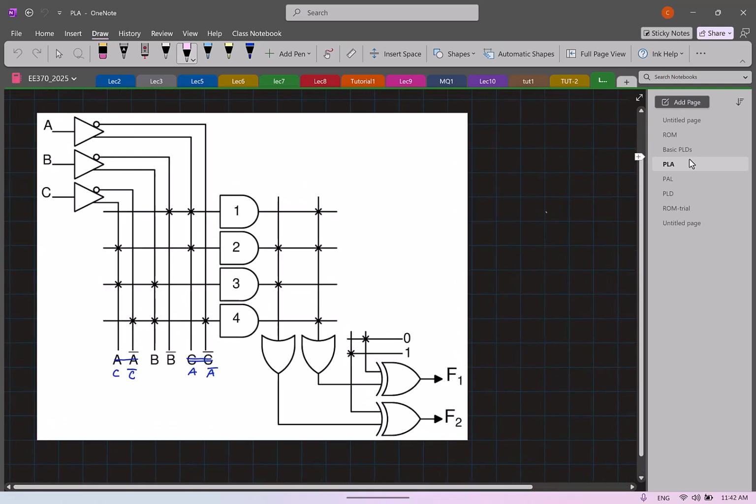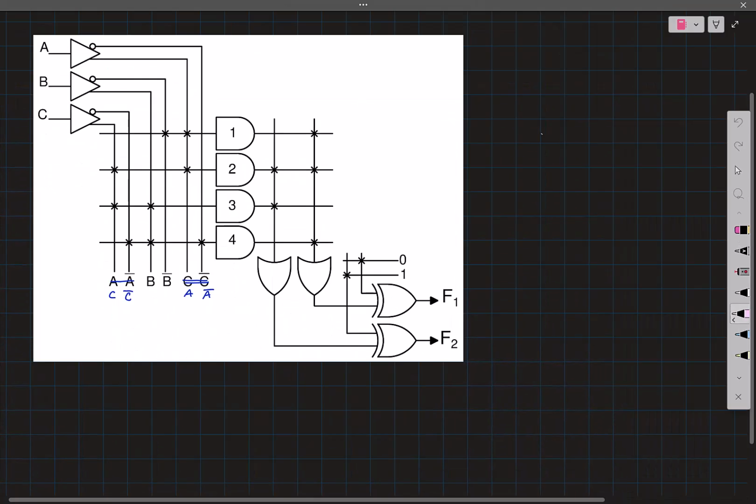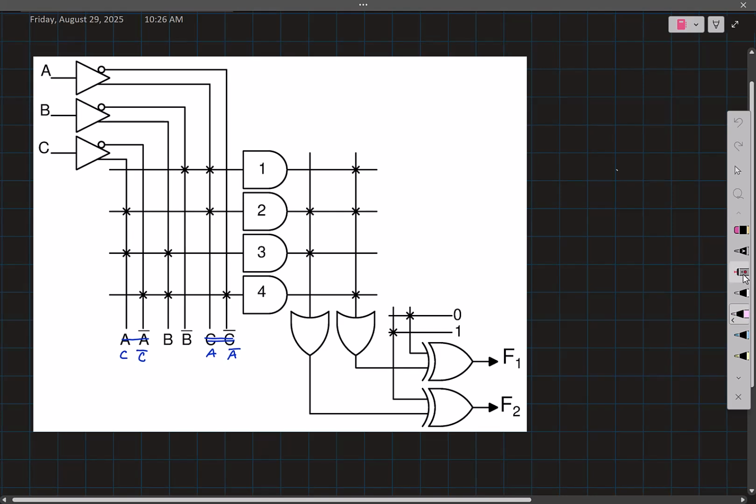First we can deal with a programmable logic array, then I'll show you a programmable array logic. So the programmable logic array, the most flexible arrangement: you can see that you have an array of AND gates where the inputs to the AND gates are programmable. You decide whether to short and connect to a particular net or not. Similarly, you have an array of OR gates where the inputs to the OR gates are now programmable.